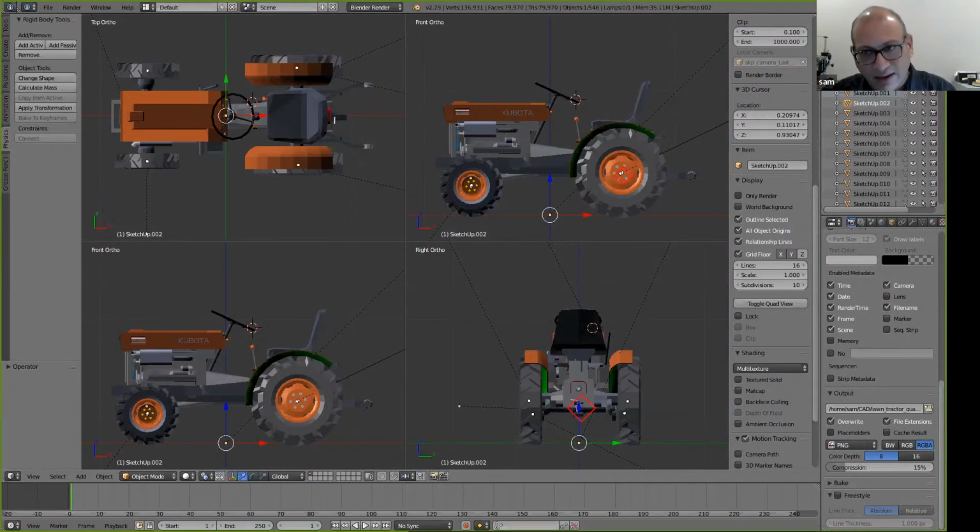Right. Now your link has a visual, which you're defining via the link element. So you don't leave it empty. If you leave it empty, it will assume that it has no geometry associated, and it will not render anything, and it will just come up empty in RViz, just a virtual link. You don't want to do that. You want to give it a visual. In most cases, it is really important. When you give it a visual, you can use either primitive objects like a square, sphere, or rectangle, or you can also use the mesh file, which is your CAD file. In this case, we wanted to use the CAD file for the link.